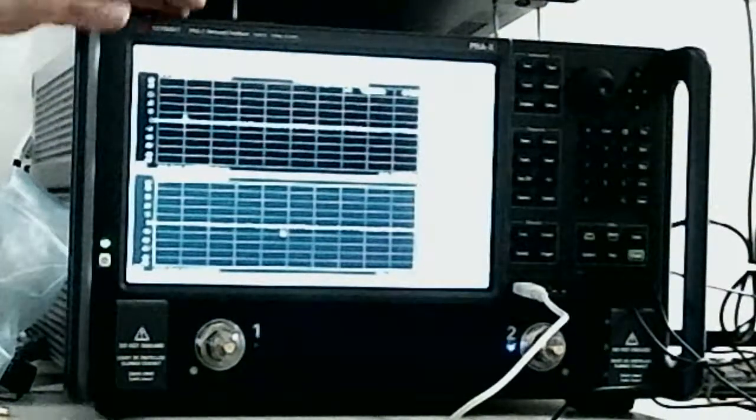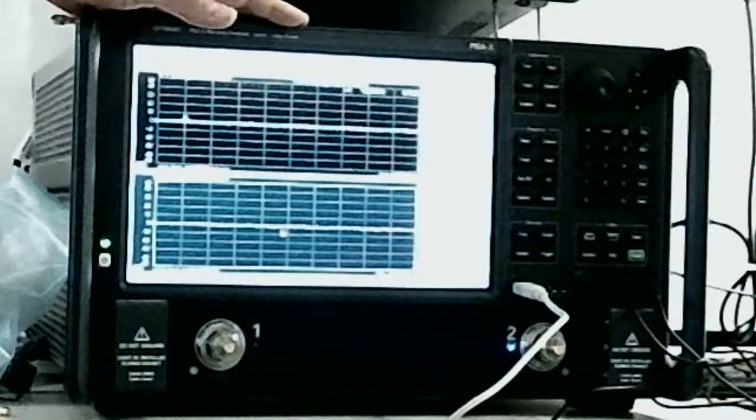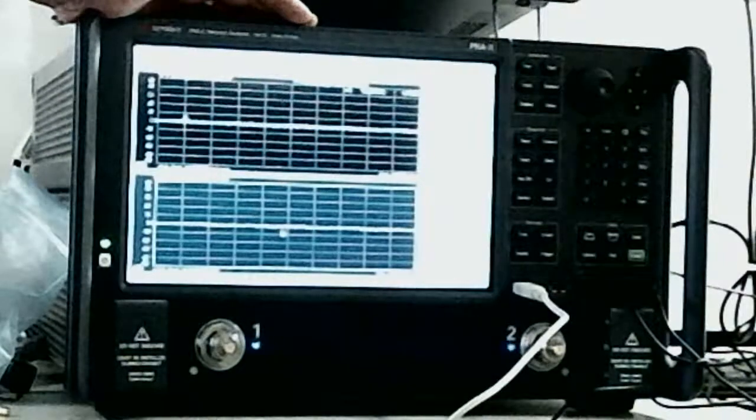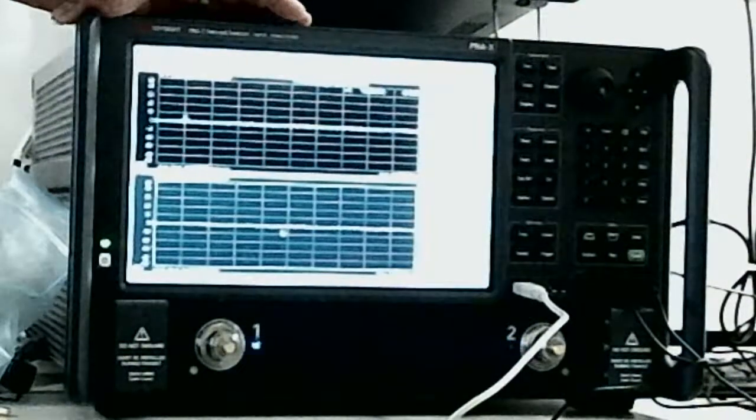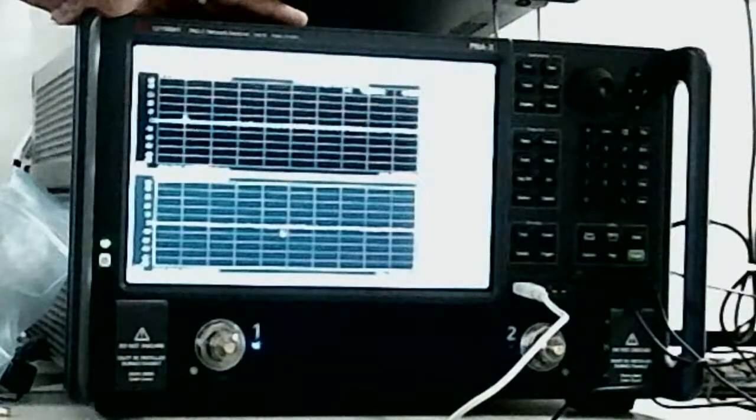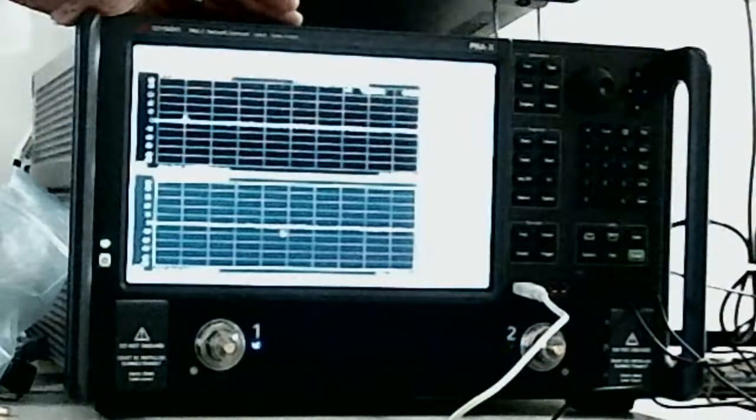So I can create a new channel. This is a completely different set of stimulus. I can do it at a different power, different frequency. And channels are basically stimulus conditions for your measurement. And you can have up to easily 99 of them on the network analyzer. So you can have a lot of different measurements going at the same time. So you can do 99 different power sweeps. So if you wanted to get that full extraction, where you can do the different frequency sweeps or different power sweeps, I'll show you kind of how to do that, right?